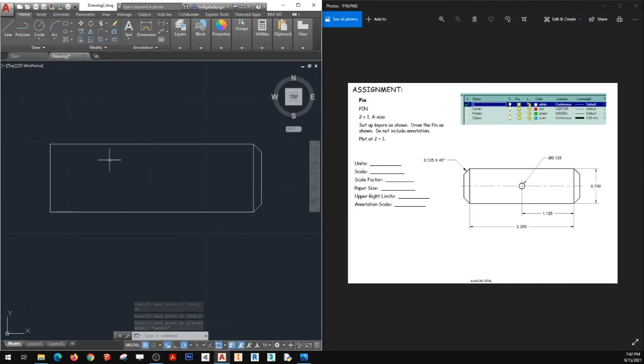So to get them over here, I could do the same thing, or I could use the mirror tool. Lots of parts have symmetry, so the mirror tool comes in handy. I'm going to green box to select my 3 lines. I'm then going up to my modify menu and clicking mirror. When I click mirror, this is another modify menu option, so you've got to read the command prompt. Specify first point of mirror line.